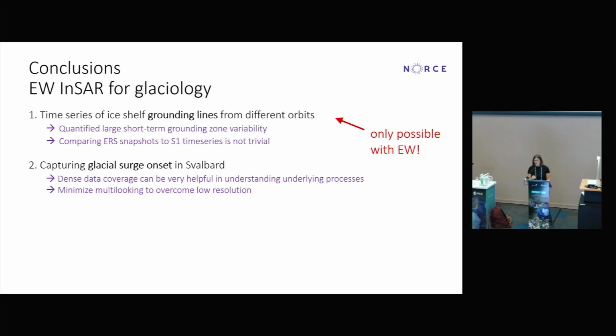And just a note that we use a quite small multi-looking factor to overcome the low resolution, and still it's relatively good coherence on many of these interferograms. So that was actually a surprisingly good coherence even on 12 days interferograms.